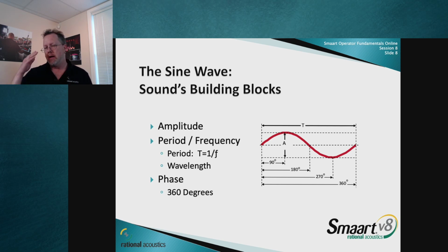So I'm going to look at the 1K on the input of the system, the 1K on the output, and I'm going to say, okay, we've matched. We've got the same period, the same frequency. So, okay, how loud are you going in? How loud are you coming out? That's going to give us the magnitude response. And then we're going to say, where are you in the oscillation?